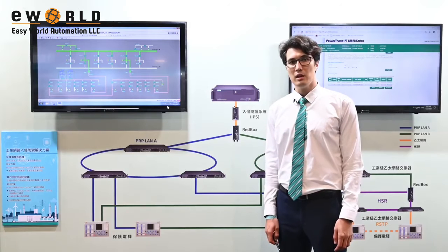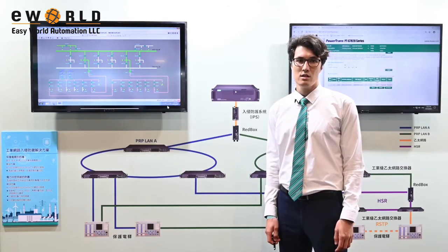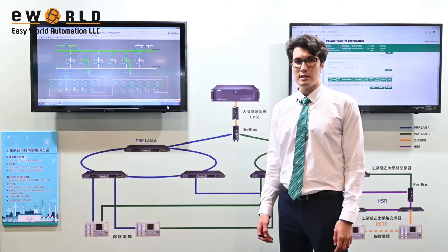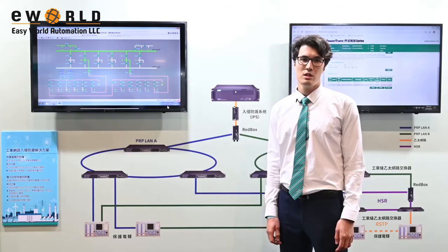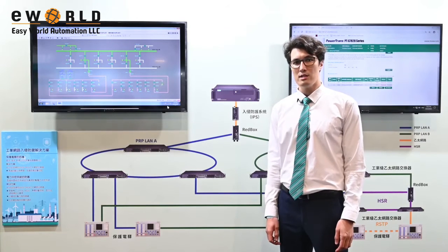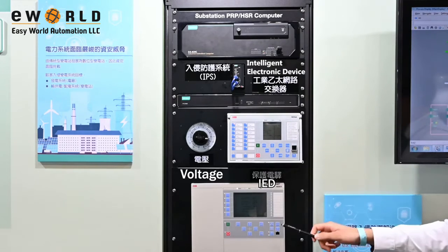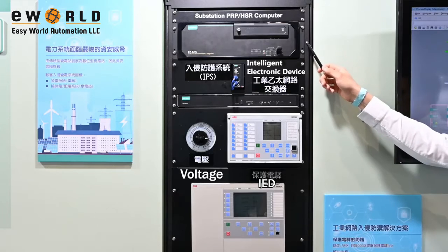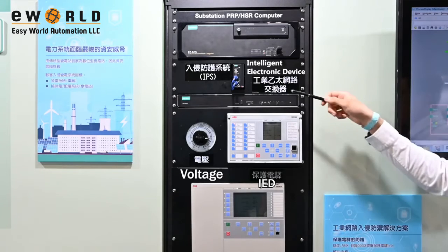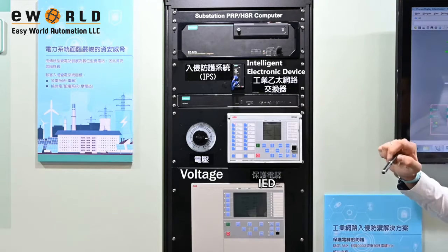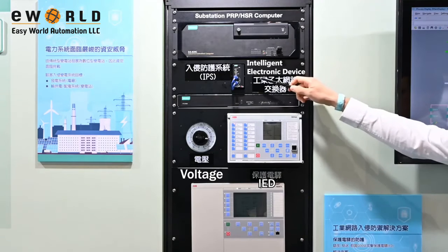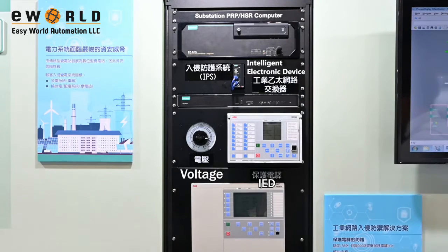The attack vectors may include compromised WAN links, as well as internal attacks through removable media or other unauthorized devices. Let's see what may happen if adversaries get access to the substation network. We have built a test bed consisting of 2 IEDs and a SCADA server, which are connected through an Ethernet switch. Also, we have an additional cybersecurity appliance here, which we will introduce later.